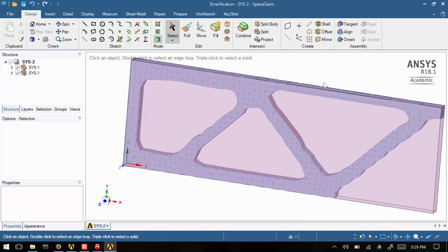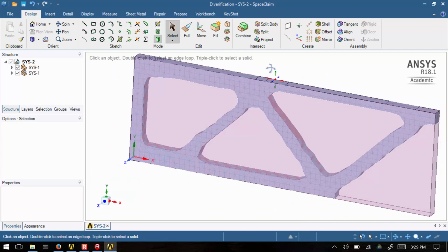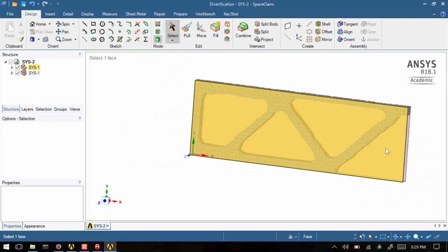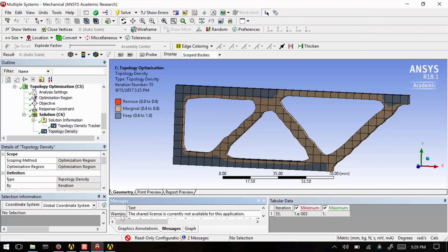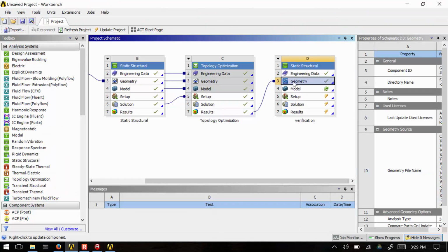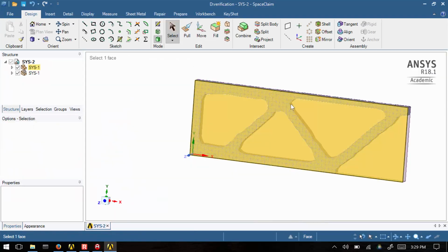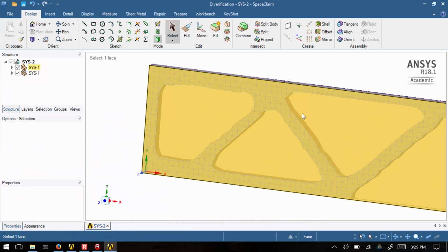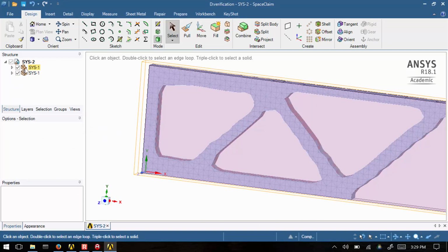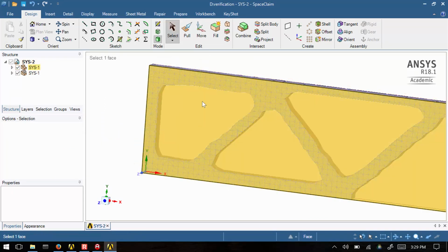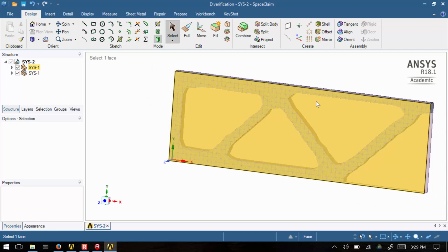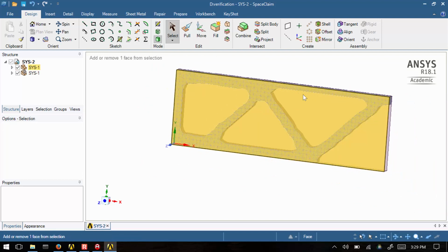So what it's giving me is my original geometry, and the reason I can't just click on, if I go into model now, I'll just get my original geometry, which is not going to help me. I need to convert this SpaceClaim mesh into a solid, okay? So it has on the left, and SpaceClaim allows me to quickly do that and allows me to clean up the geometry pretty easily so I can get something that looks reasonable.